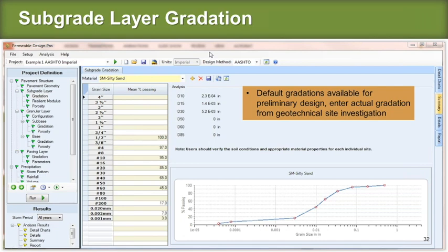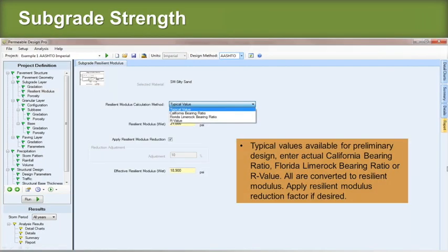And so when we do some calculations based on that, the defaults are there for you to use and they're reasonable. But if you're actually designing and going to build a permeable pavement, it's strongly recommended. In fact, both of the manuals that I showed you earlier will tell you some information about how much testing you should do. In Alston Way, we dug test pits through the road into the ground and did permeability testing of the ground. We want to know what the structural capacity is so we can do testing of those materials. So the defaults are fine if you're doing a preliminary design, perfectly fine. But if you're going to do an actual one, you should do actual data. You should actually go get lab data and select your own information for it.